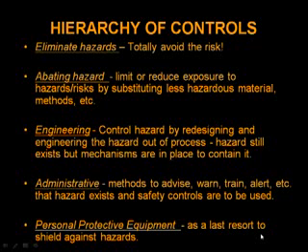The hierarchy of controls provides a method to rank the potential controls to be evaluated. By using the hierarchy of controls, you develop a tiered approach to the evaluation and reinforcing of your safety system. The hierarchy consists of step 1, looking at the hazards and determining whether or not they can be totally eliminated or totally avoided. Can we eliminate this risk and the associated hazards completely?